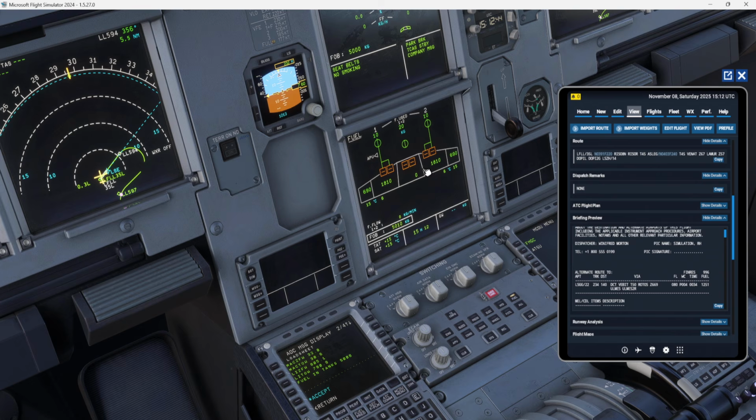And also during flight, because we calculate the zero fuel weight, you need to know that during flight the fuel consumption of the Airbus A320 makes the center of gravity move forward. So during flights it moves forward once we are burning more and more fuel.